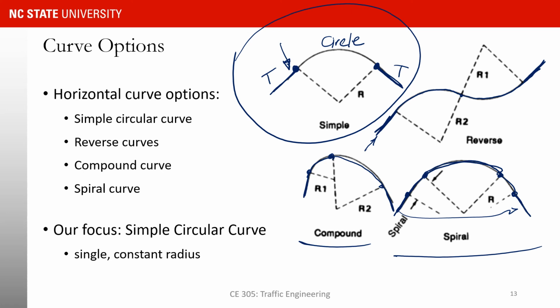So there is a curvature of 0, and then we smoothly transition to the curvature that we have here, that is the curvature of this radius, or this circle. And so as a result of this parabola, you have a smooth transition and you don't need to turn the steering wheel abruptly.